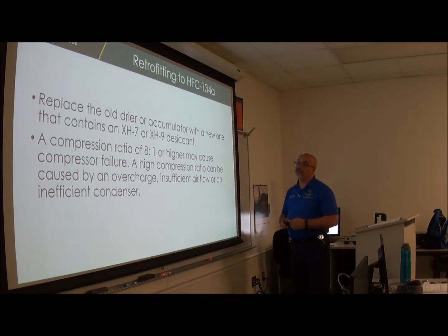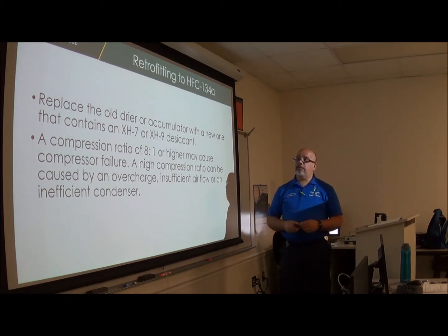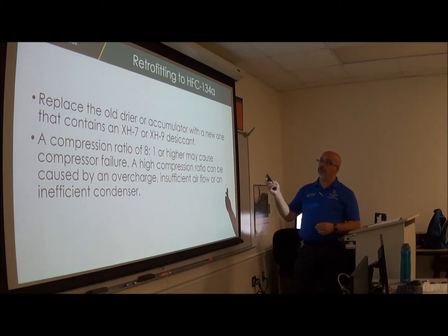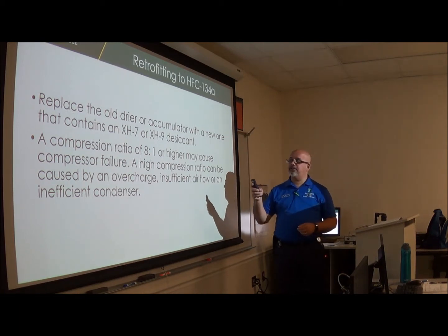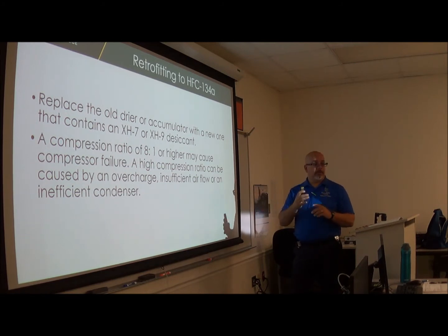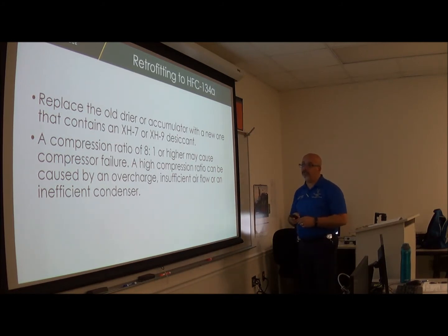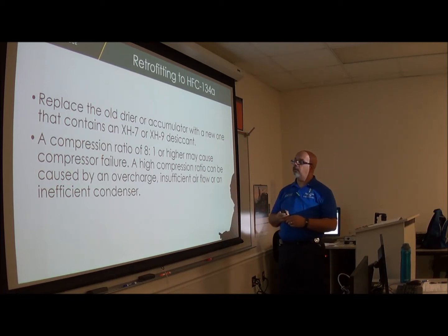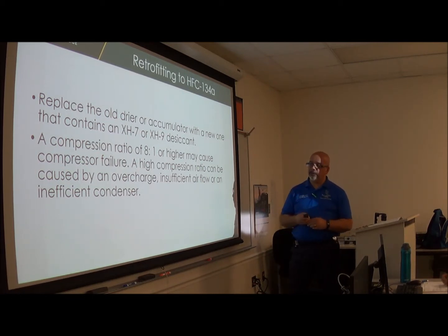Retrofitting to HFC 134A, you would have to replace the old dryer or accumulator with a new one that contains an XH7 or XH9 desiccant. That's what I was mentioning about replacing the dryer, the O-rings, and then putting the adapters. A compression ratio of 8.8 to 1 or higher may cause compressor failure. A high compression ratio can be caused by an overcharge, insufficient airflow, or an inefficient condenser.